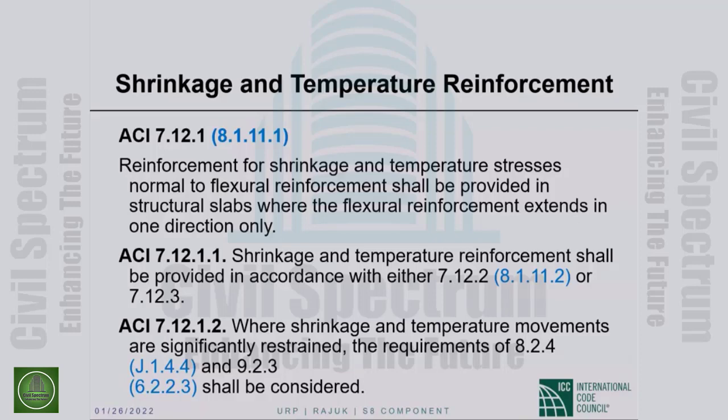Where shrinkage and temperature movements are significantly restrained, then it's a different story. Then you have to consider the stresses that can be caused by the restraint. Now it's a substantially different story. So the shrinkage and temperature reinforcement is fine when the shrinkage can basically take place.